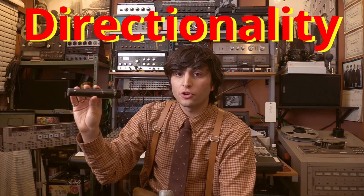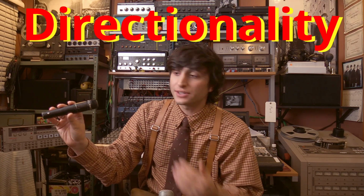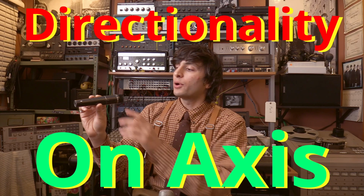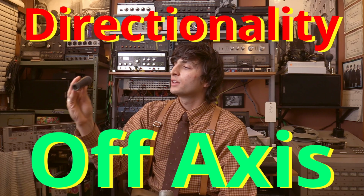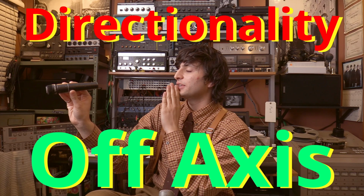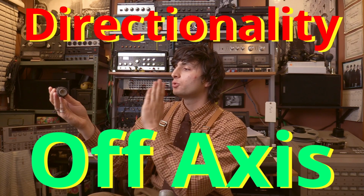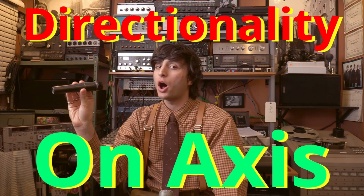Normally, when we think of a microphone, we think of pointing it directly at the sound source that we're trying to capture. In this instance, if I'm talking into this microphone, I'm going to be talking 0 degrees on axis to this microphone. But we need to consider the off-axis sounds. When I say off-axis, this would be 90 degrees off-axis. The sound coming from the back of the microphone would be 180 degrees completely off-axis. Turning it 90 degrees more would be 270 degrees off axis, and once again back to 0 degrees on axis.